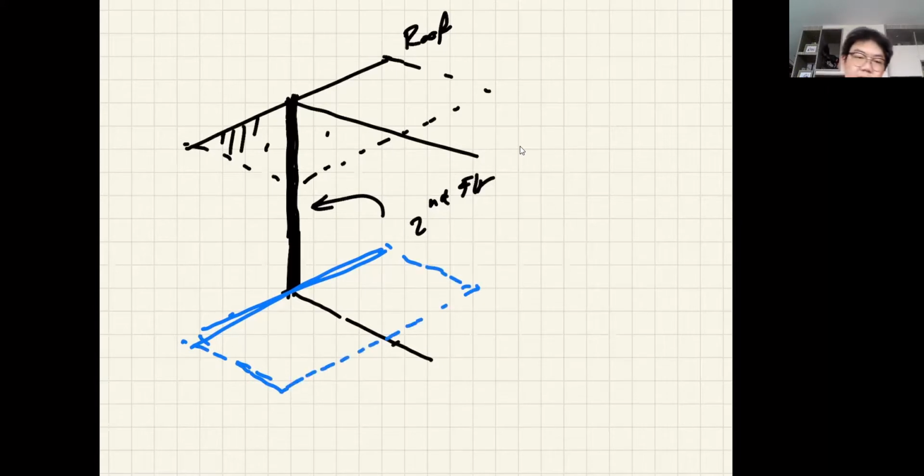And you see very clearly from this picture that the load on the roof goes into this column. See, the load on the roof is black, and the black portion of the column will take care of the load from the roof. And then when we are at the second floor and we continue to move downward, that will be the portion of the column underneath the second floor. Okay, and this one will carry the load both from the roof and then from the second floor.